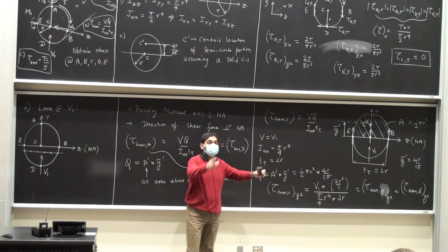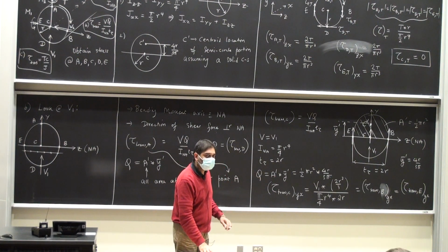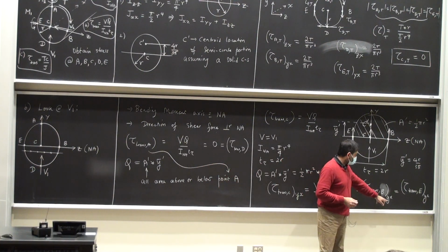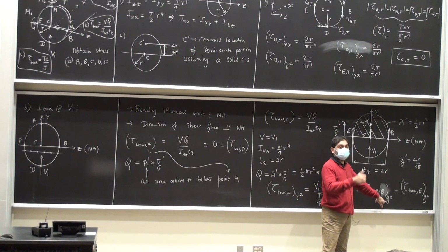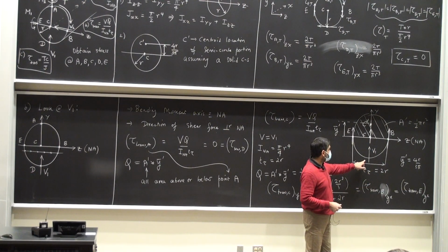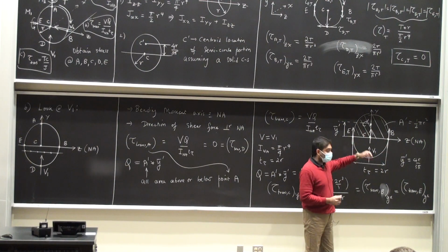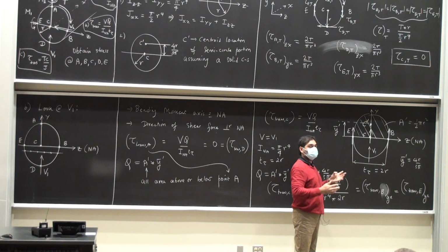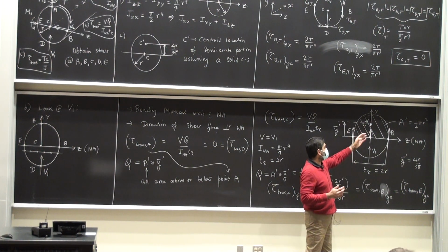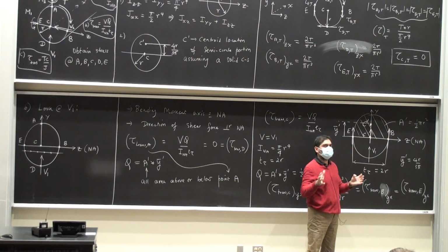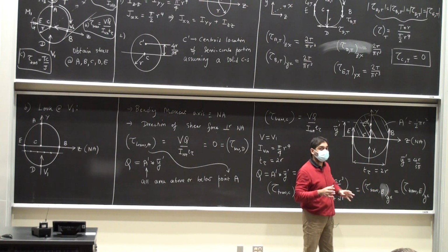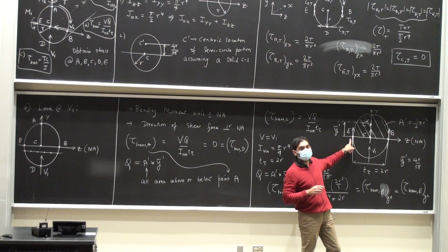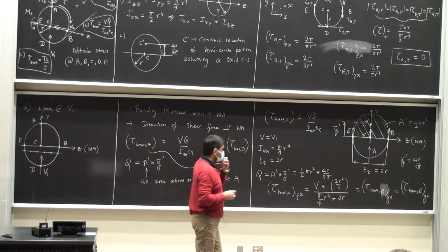Is everybody on the same page? Yes, question. Can you explain the yx after the trans B, the trans E, and the trans C? Oh, sure. So, the first subscript is the direction of the shear force, which is V1, which is pointing along the y-axis. The second subscript is the direction of the area normal to the cross-section. So whichever is the axis that is normal to the cross-section, which is the x-axis is into the cross-section, but we are not worried about the directionality from the negative positive point of view, just the suffix. Because we are anyway drawing the direction of the figure here. Okay? Alright. Any other thoughts?